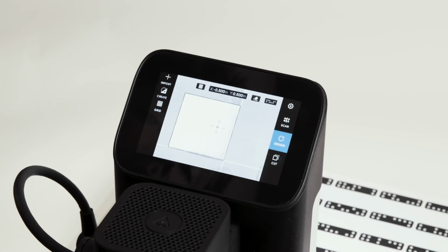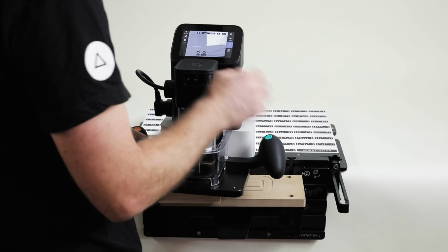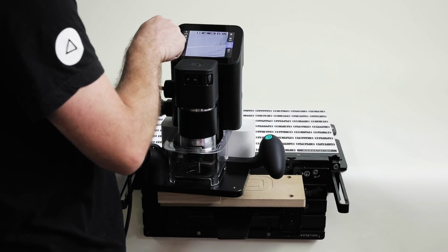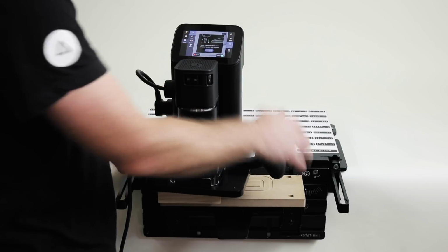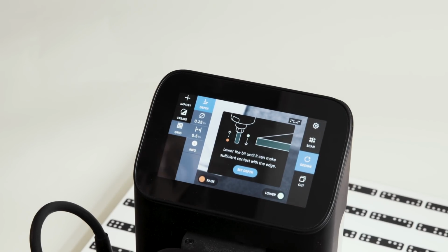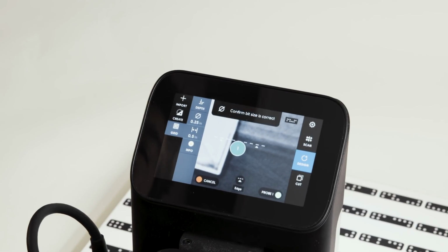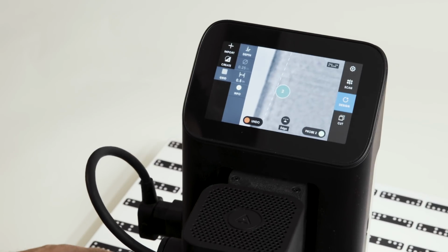Pretty powerful. So now we're going to come around and probe this outside edge and the top and show you that it's just exactly the same process. So I'm going to come out beyond the edge, lower my cutter. Once it's able to contact my surface ever so lightly to avoid inaccuracies, I'll accept the depth, and then I go probe once, and then I come up,